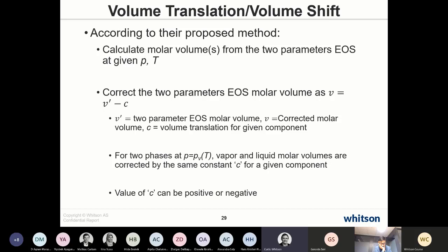So he had basically a 5-parameter type tuning process, and he showed for almost 15 complex reservoir fluid systems that he could match very complicated phase behavior of gas condensates, oils, and so forth with basically these 5 correction terms. But he changed the A and B of methane, for example, by a factor typically of plus or minus 20 to 30%, and a similar correction for the C7 plus components. And a lot of people were very uncomfortable with doing it that way, but it did get the job done.